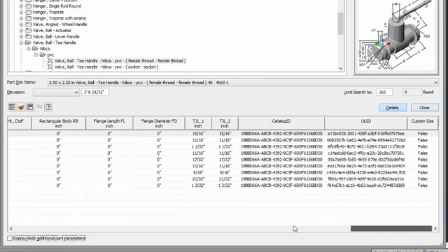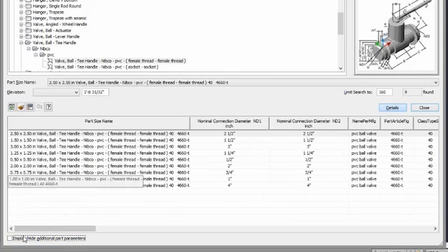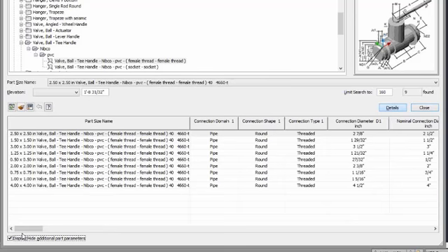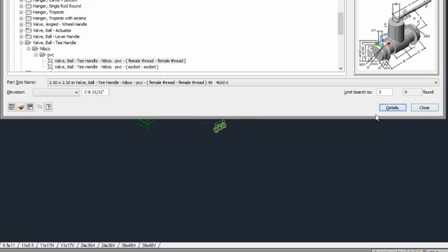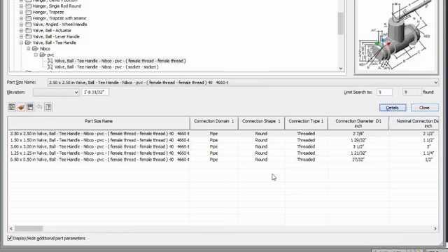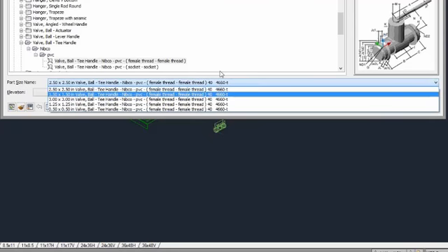In this case, a lot of the parts parameters are set to be displayed. Some of them are not. You can see a lot of these three items here drop off when I check and uncheck this. Here you can see that there are 9 items found. I'm looking for 160, but if I had that set to 5, you'd see now that only 5 items show up, even though there's actually 9. So you might think that that part is not in your catalog. So pay attention to that. That's kind of a big deal. And of course, you can uncheck the Details tab if you don't want to see things down there, and choose your part from the drop down here.